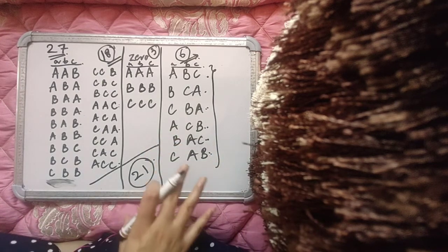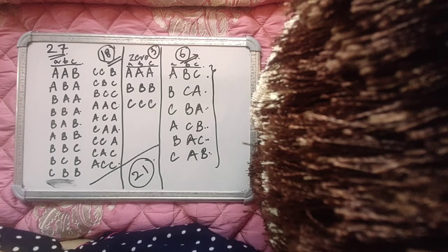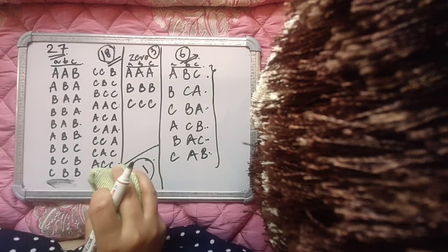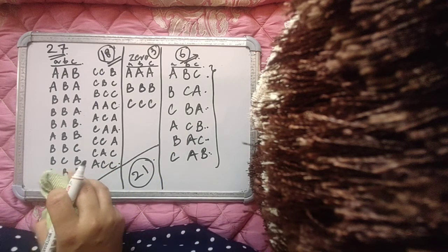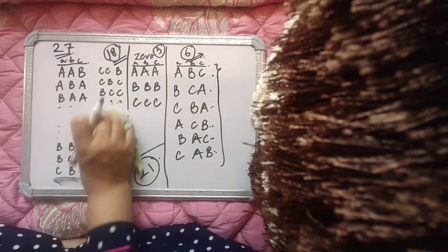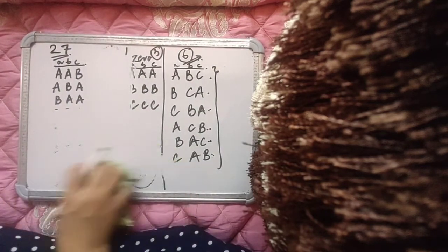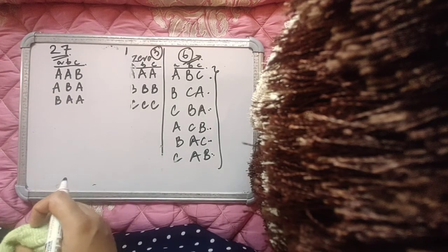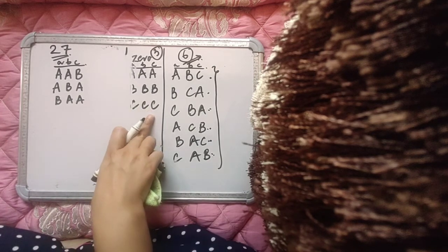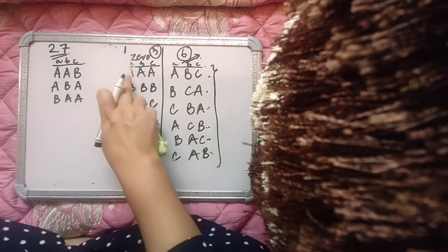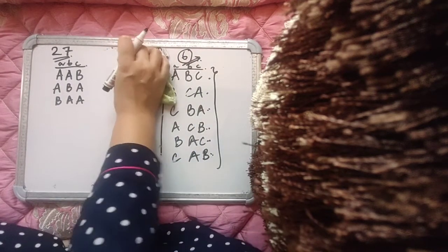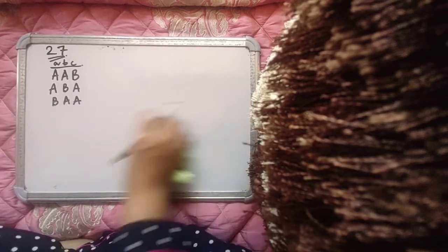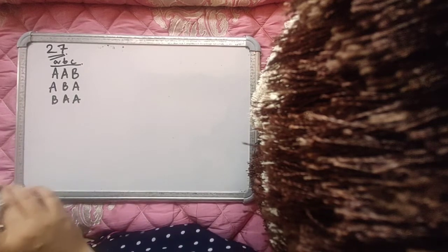So let's try to construct the space vector diagram, the line to line voltage space vector diagram, right? Now I'll retain only 3 states because I can't repeat the space vector analysis for all the 18. You can do it as a home assignment, but these 3 states I will retain, only the top 3 states of the 18 vectors. The 0 vectors, I know they will result in a position at the origin because the line voltages are all 0, so I can delete them, right? Let's try to construct the space vector diagram for the first 18 states, out of which we have retained only the top 3 states.